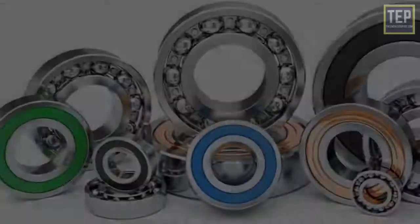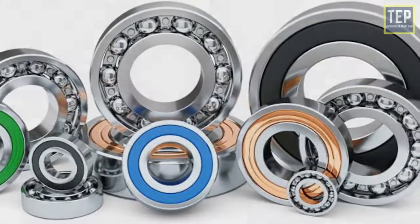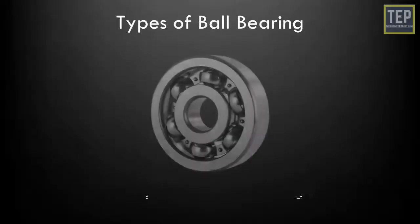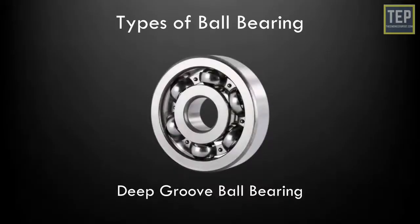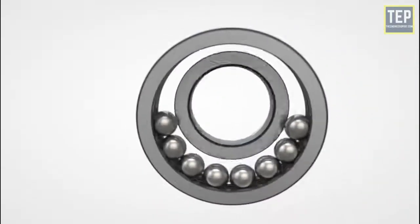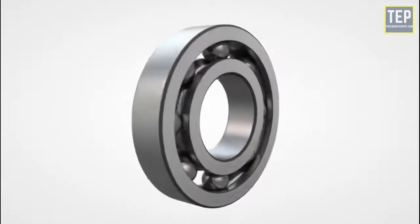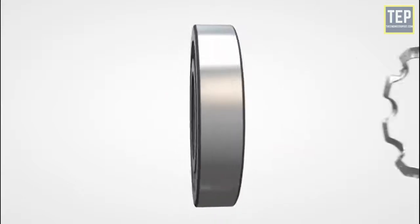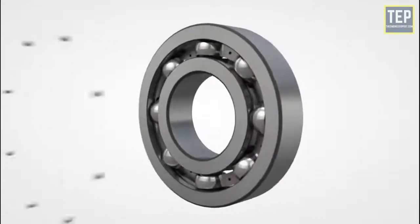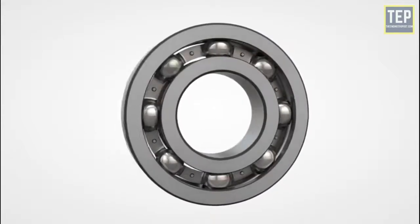Depending on the application, different types of ball bearings are available to choose from, such as deep groove ball bearings. This is the most widely used ball bearing. Trapped between the two races is a ring of balls that transmit the load and allow rotational motion between the two races. The balls are held in place by a retainer. They have very low rolling friction and are optimized for low noise and low vibration.